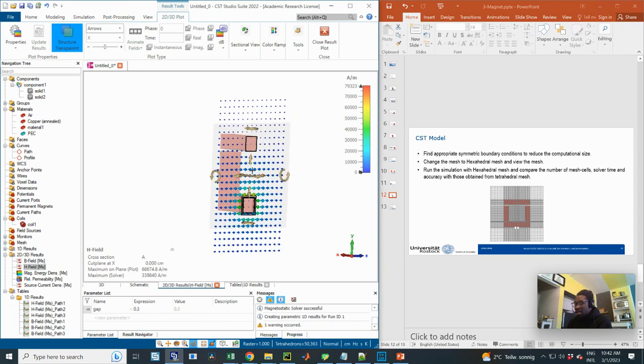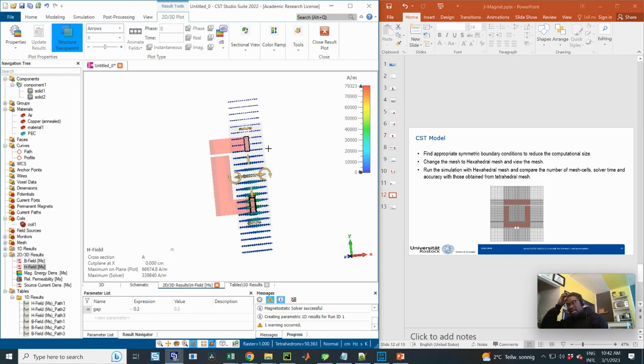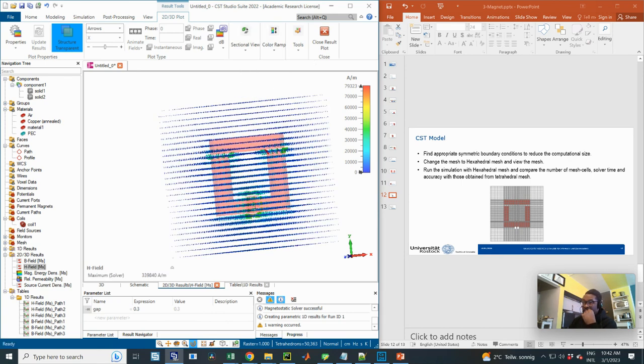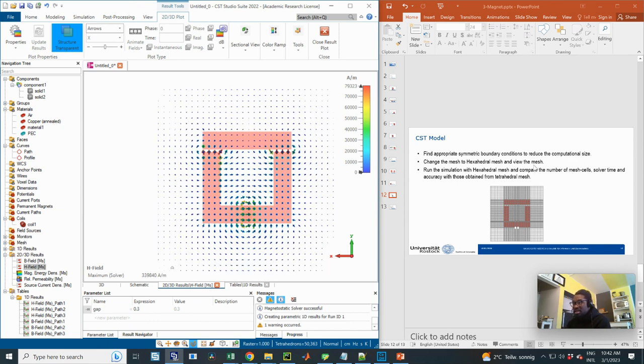Now you just have to go ahead and observe the field profiles. Of course you can see here that you have just normal components. So your H field is normal to this plane, which means your tangential component is 0, so Ht is equal to 0. So you could look at that and then look at the previous examples and apply the proper symmetry boundary conditions. So I'll leave that as an exercise. One way to check your answer is to see the results before you apply the symmetry boundary conditions, and after, they should be exactly the same.